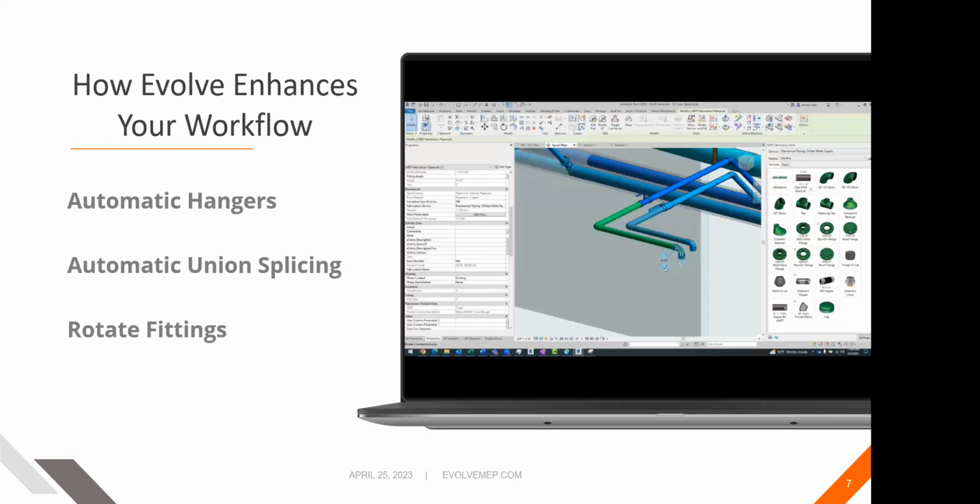Whereas Revit sheets are all based around the levels and sections you create within 3D. So if something in 3D changes, that's going to change automatically on your sheet. If you have a mechanical equipment tagged with a number or value, and you change that mechanical equipment to a separate mechanical equipment, that tag stays there.